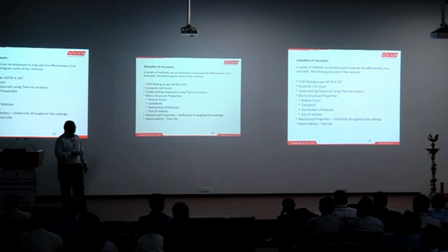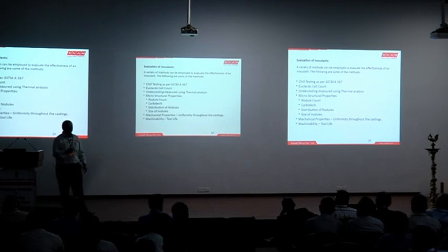So this is a direct measure of the number of nuclei available. So it is expected, or it is bound to increase after inoculation, and any changes with respect to the melting practice or temperature gradient, eutectic cell count alters.